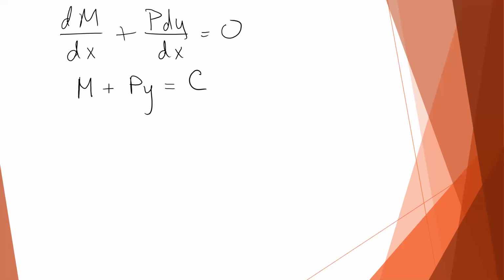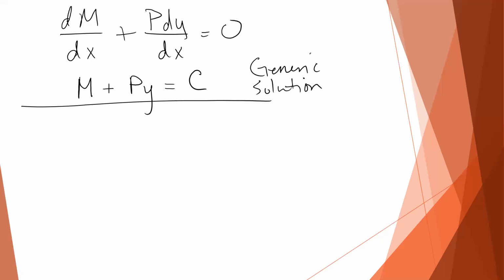Now, up until this point, everything has been generic. I gave you boundary conditions of the roller and the pin, but they haven't affected our solution. No matter what types of reactions they were, they would not have had horizontal forces. And so we still would get the 0 shear. Nothing would be different if you changed those boundary conditions. So up until this point, this is a generic solution. But we're about to customize it for our boundary conditions.